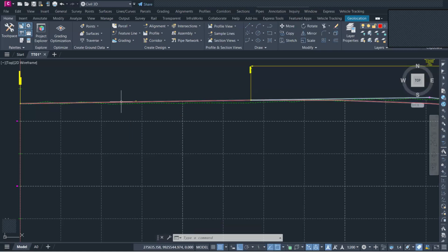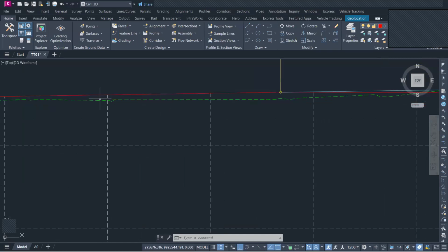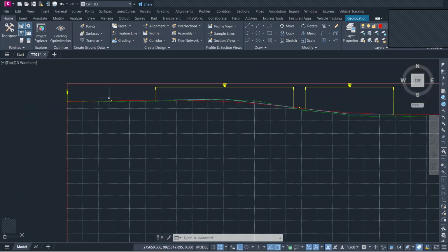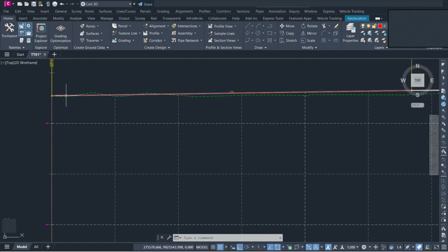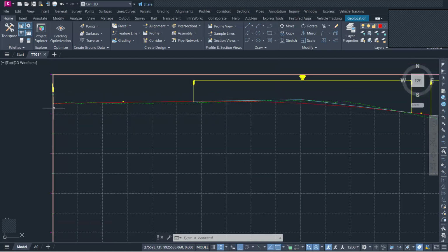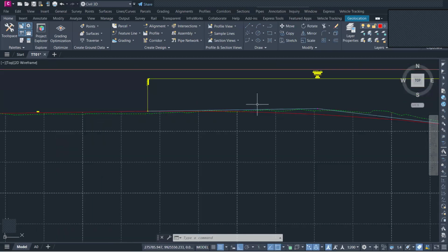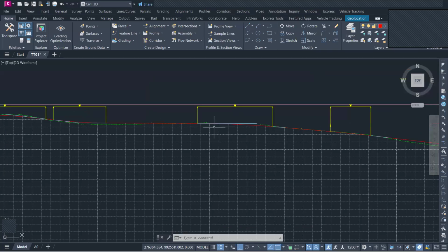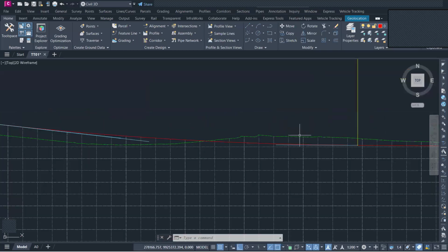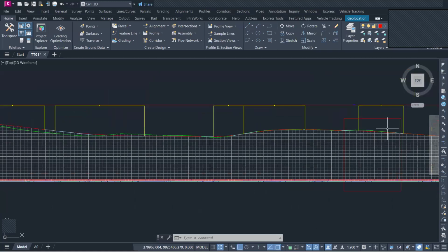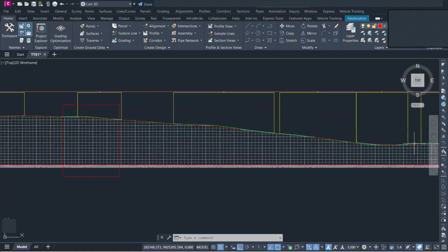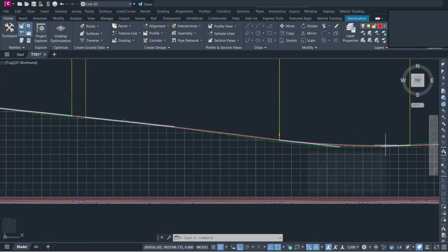In such a scenario, what you do is you're just leveling the ground. That is what you are doing. You will say the layer is already good enough at this point. Remember, the layer is already good enough. So you're just leveling it. In sections where you need to cut, you cut. In sections where you need to fill, you fill. Whatever you're doing here, you do it along the entire section. That is the first scenario.